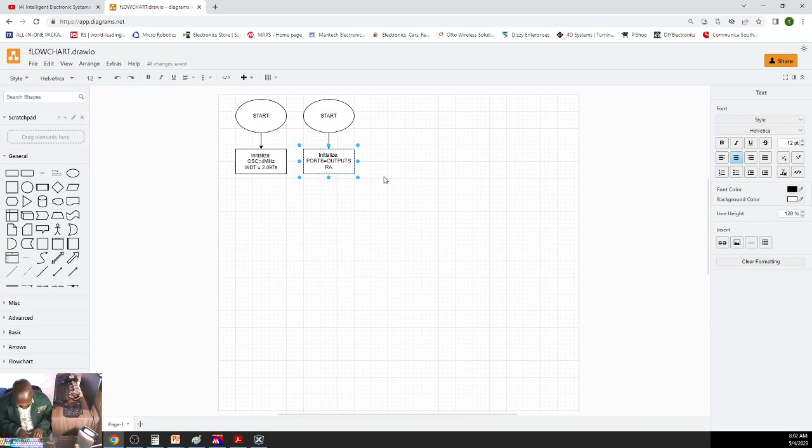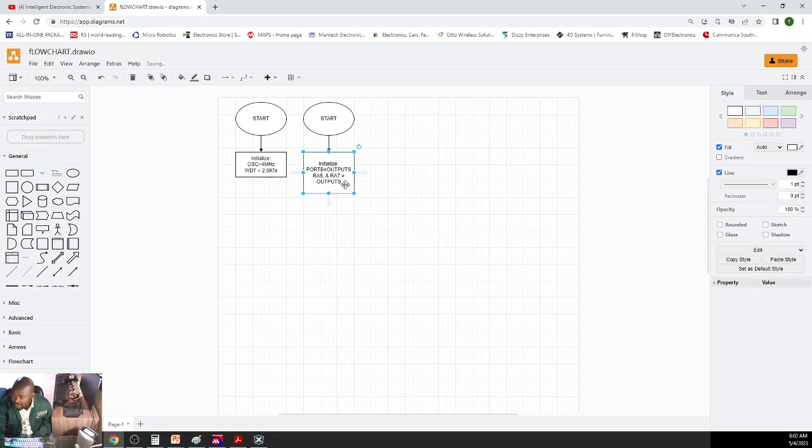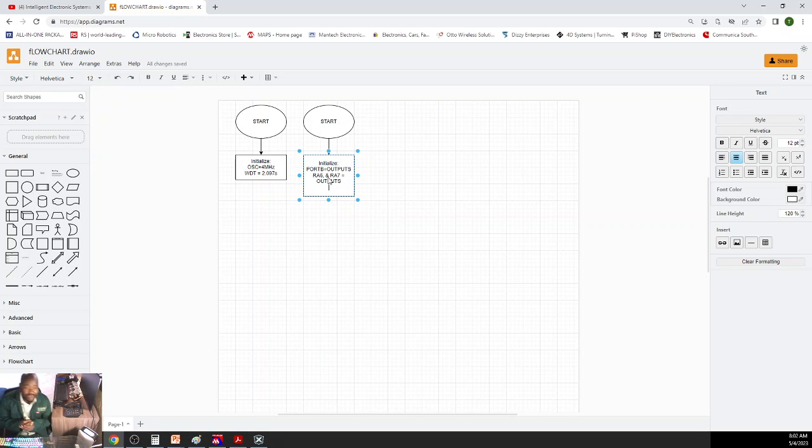So RA6 and RA7 must be outputs, right? And then, because I'm going to use timer 0 interrupts, I need to perform timer 0 calculations to say after how long will I have an interrupt, so that with each and every interrupt I can switch between the 7 segments, right?